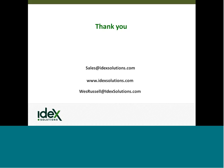Good. The tool management. You selected a tool holder, and it automatically selected the associated end mill with the holder. Can you maintain a separate tool holder catalog and tool catalog? I don't use catalogs very much in V6 because the data has to be in the database even to put it into a catalog. So why maintain both? As you saw in the icons, I can either access them from a catalog or directly from the database.